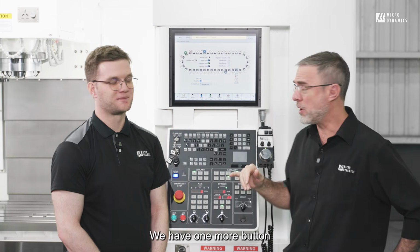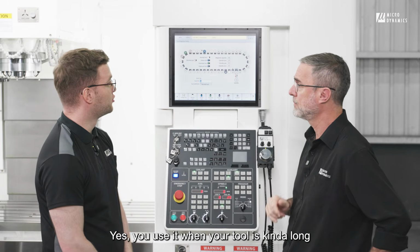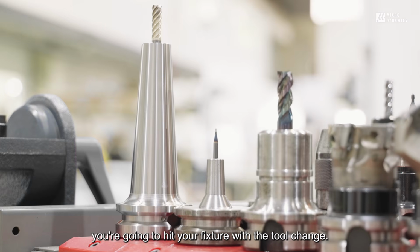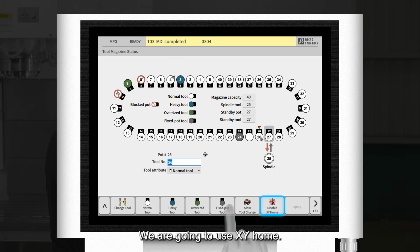We have one more button here, it's the XY home position. Yes, you use it when your tool is kind of long or you are worried that you're going to hit your fixture with the tool change. So for example, let's choose tool 26. We are going to use XY home.